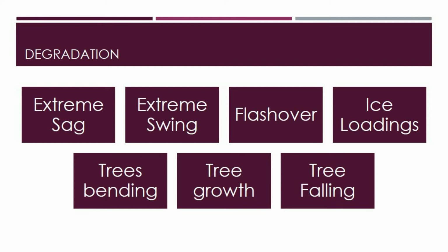And speaking of branches or trees, the bending of trees into lines due to wind is also another issue. Next is the formation of lines of bushes or trees within flashover distances, which will impede and pose issues to an overhead line in its right of way. And lastly, the falling of trees in such a way that part of the tree infringes on conductor clearance during or after the fall, regardless of the circumstances, would cause problems for the right of way.